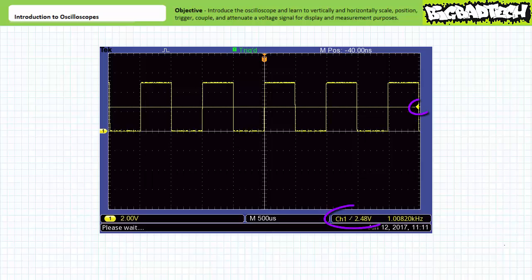For example, if we triggered not at 1.2 volts going positive, but rather 2.48 volts going positive, this just means the oscilloscope uses 2.48 volts and rising as our one beat. To adjust the trigger level, one uses the triggering knob. When adjusting the triggering level, you'll see the level rise or fall. As previously, every time the score hits the one beat, in this case 2.48 volts, the oscilloscope captures a window of data and displays it on the screen. Really nothing has changed, only the repetitive waveform is being sampled at a different moment, thus shifting our capture window ever so slightly.